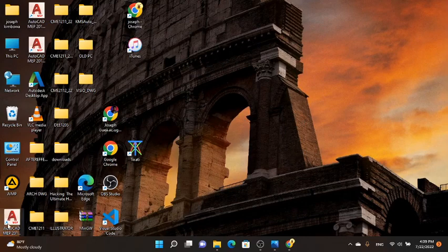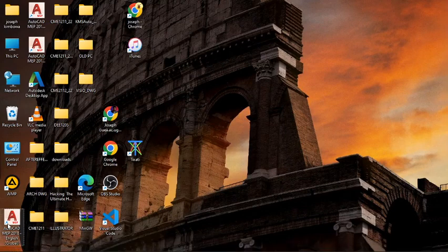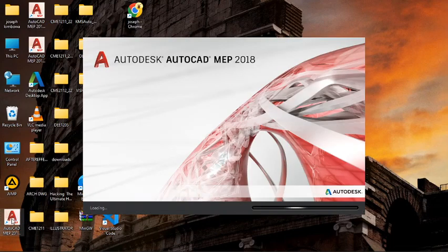Make sure you are using the right workspace shortcut. Usually with AutoCAD MEP you have about 3 shortcuts. You have one for English Global, English US Imperial, and US Metric. You click on the one that says English Global, because if you're the rest of the world and not US, it takes you directly to the necessary shortcuts.